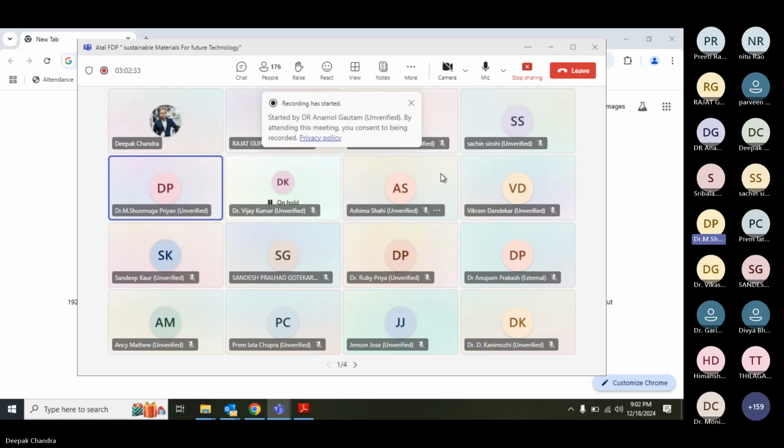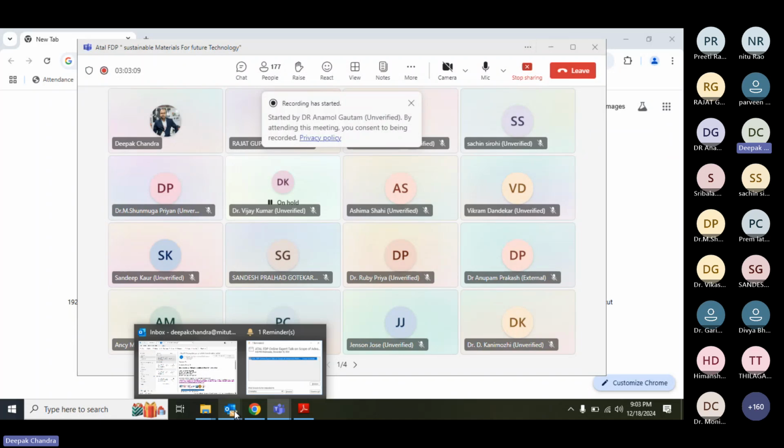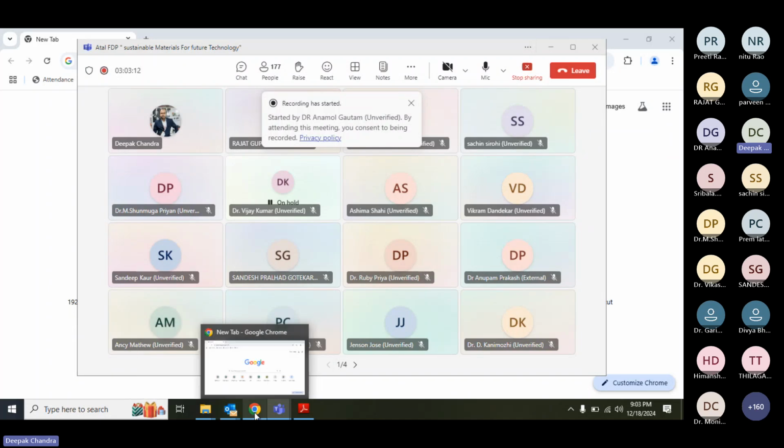Straightness and flatness are basically parameters of GD&T. Straightness and flatness can be measured easily by a few instruments like linear gauges and the 2D height gauge. I explained about the 2D height gauge. I will show one video. I think from that you will understand how straightness and flatness can be measured, even perpendicularity of a component.